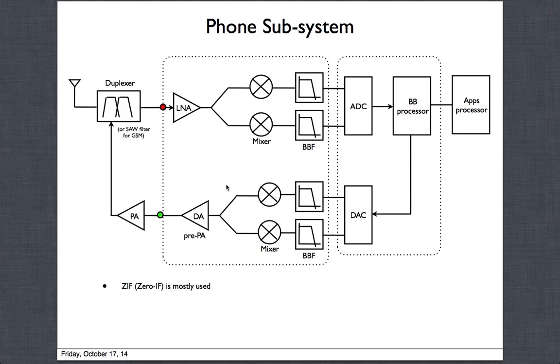But let's look at what the RFIC, the transceiver, has typically. Typically they are all 0 IF transceivers now. It's been many years, way over 10 years actually, that all the problems of 0 IF have been sort of overcome. They have either been minimized or they have been calibrated out after the chip is made. You do all kinds of factory calibration to take care of it.